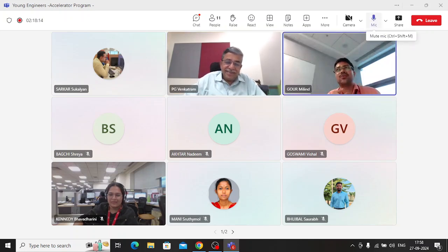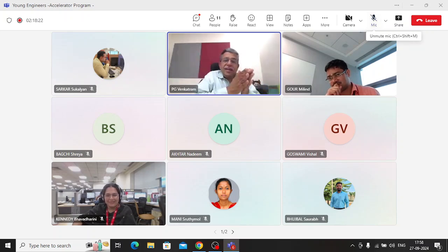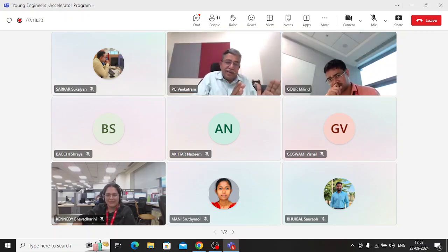Primarily we went because we are ambitious to do longer and longer spans. Slab bridges were small span, so for small spans RCC is good enough and economical. If you try to do long span RCC, it will be very uneconomical.